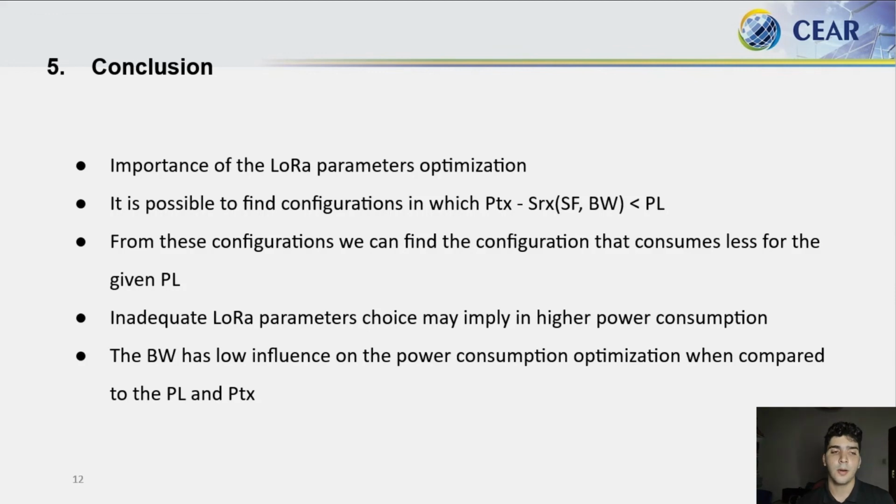In the LoRa modulation protocol, it is possible to establish different configurations which fit the needs of the system, reducing the sensor node consumption. In this work, a method was developed to calculate the optimal settings of spreading factor, transmission power, and bandwidth. This method can be used to reduce the energy consumption in sensor nodes, estimating the best setup of these parameters for a sensor node.